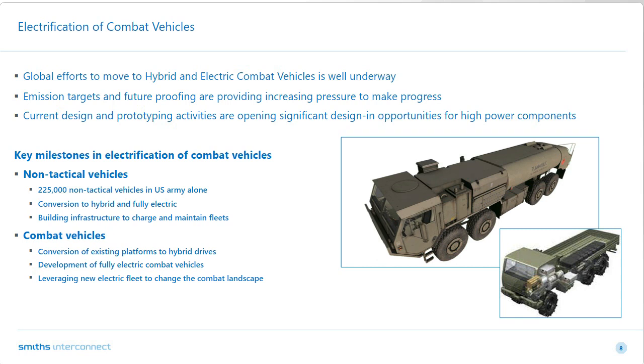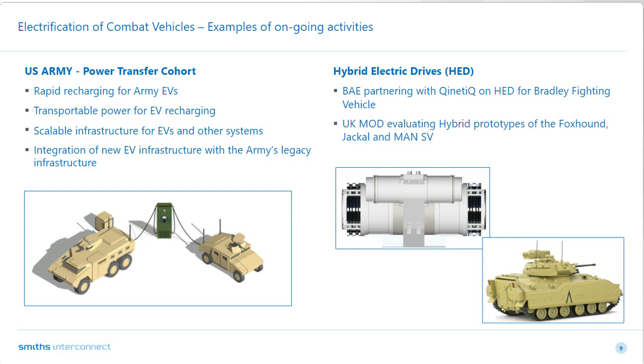It wasn't until we started looking at the electric motor differently to the fossil fuel motor that the real productivity increase came. What they did at first was drop in large electric motors as exact replacements for the fossil fuel motors, with a big drive shaft running through the factory and then smaller drive shafts tapping that energy off. It wasn't until they used smaller motors dotted around the factory, next to where the power was required, that they got that productivity increase. The exact same thing will happen with combat vehicles. If we just directly drop in an electric motor in place of an internal combustion engine, we will get some advantages, but we won't fully leverage the advantages of electrification until we change our view on what an electric vehicle can be.